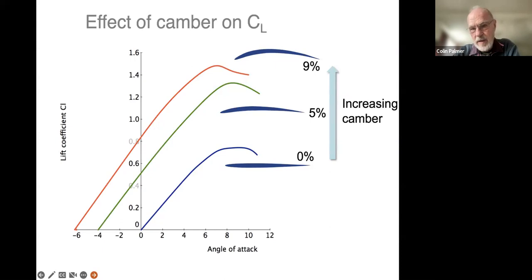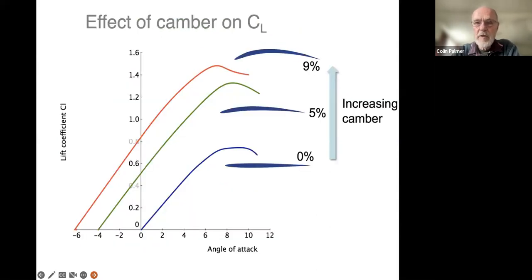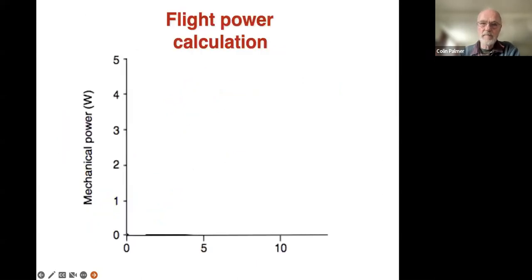And the other important thing relevant to this talk is the curvature of the aerofoil. I've just been drawing more or less symmetrical aerofoils, but if you increase the curvature of the cross-section of the aerofoil, what's called the camber in aerodynamic terms, you increase the maximum lift that aerofoil can produce. Don't worry about the terminology here, but just look at the way those curves get higher, which is a proxy for generating more lift. So if you want to generate a higher amount of lift for a given area, you need to have a cambered aerofoil, and we'll see why that's important later on.